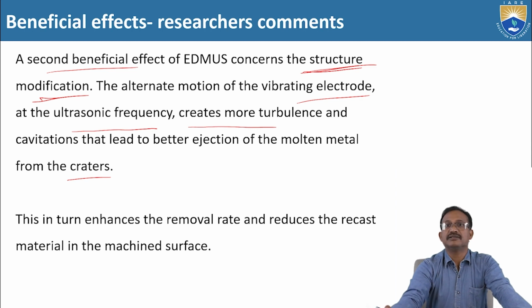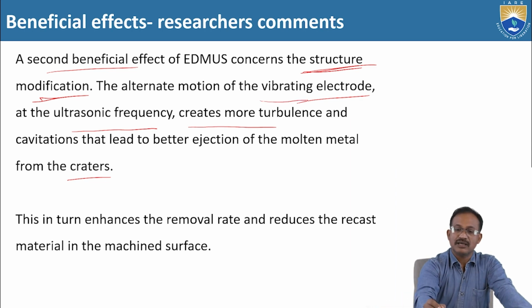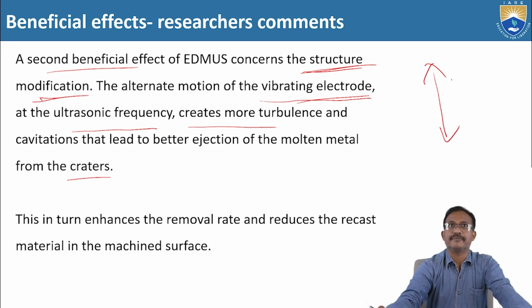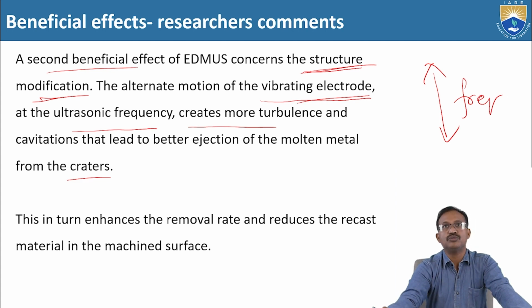The alternate motion of the vibrating electrode, that means this one, at the ultrasonic frequency creates more turbulence and cavitations that lead to better ejection of the molten metal from the craters.